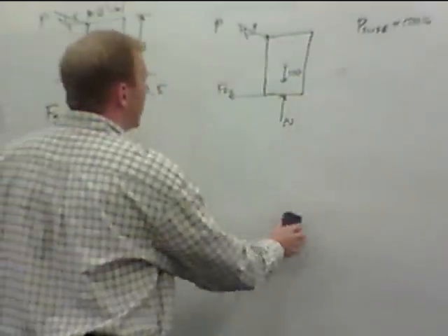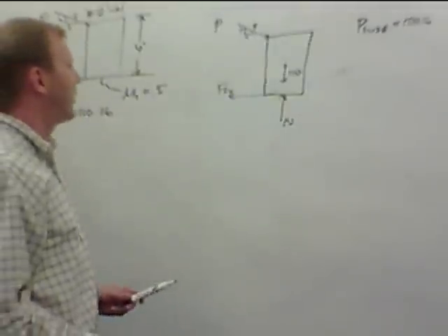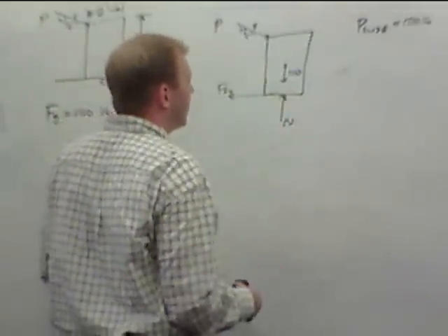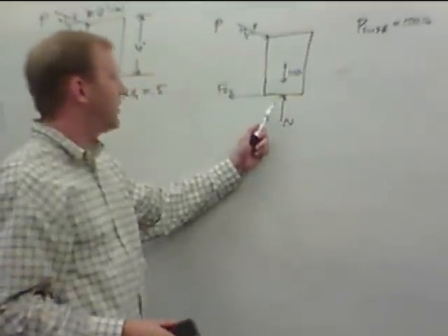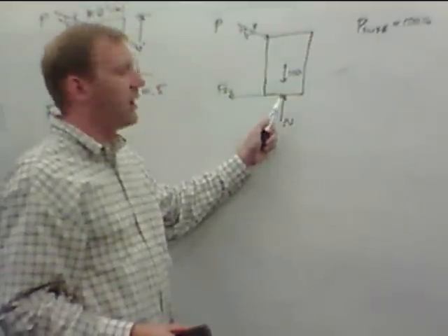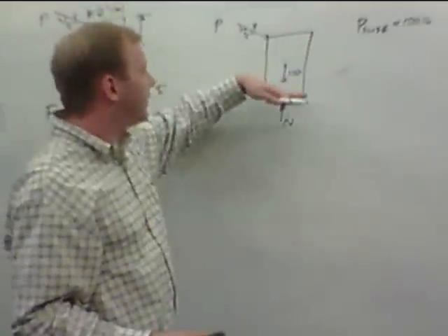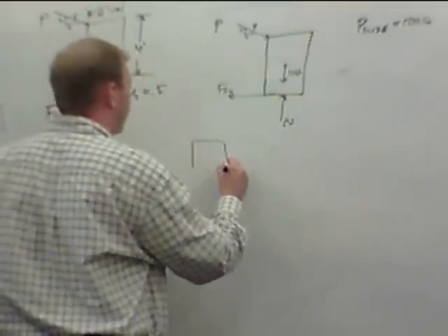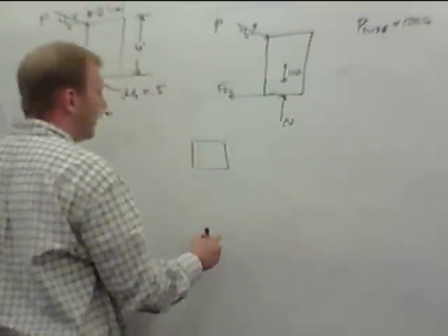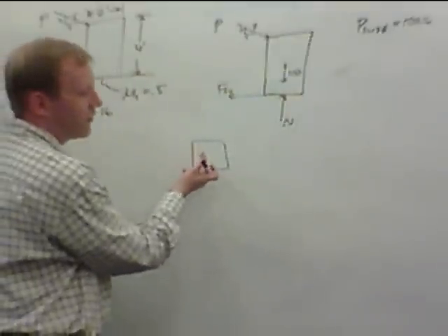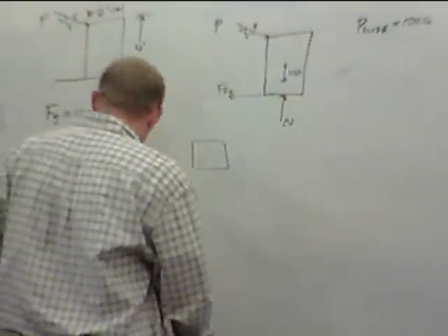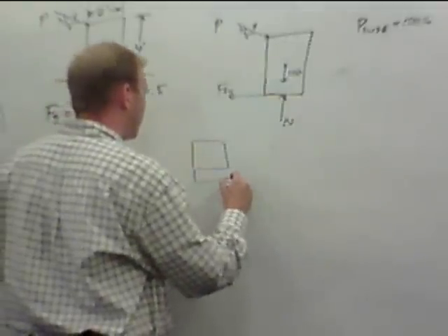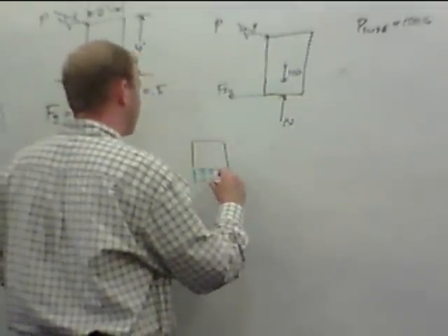Now, before we can do that, I have to have you rethink a little bit how this free body diagram works. I drew the normal force as a single force acting right on the center point. If this block is just resting here, that's fine. If you think about a block just resting on a table, that table is not exerting a force on one point and balancing it. In reality, that table is pushing up against that whole surface. You can think about it as a little bit of a distributed load.